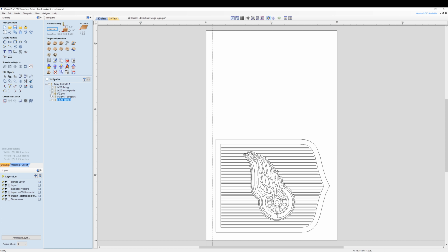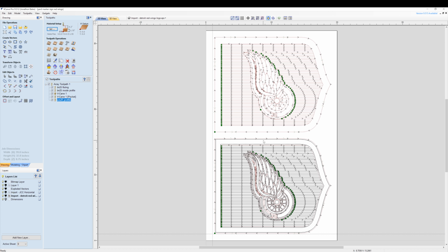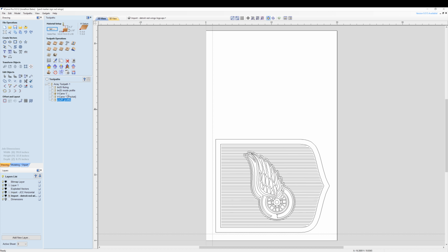I've already saved everything with all of my tool paths, and I've also arrayed my tool path so that whatever I do down here will duplicate above it and specify the distance in between. And this is a two-sided sign, so each one of these will be cut out and then glued back to back, so you see the design on both sides. What I think is interesting about it is this fluting toolpath for texture and making it go around my design and of course be contained inside the perimeter here.